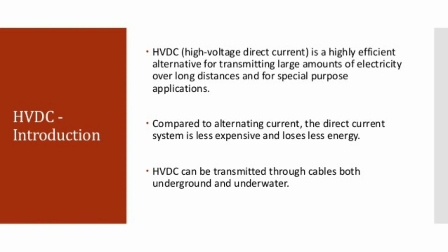But if you use HVDC system, the investment cost is lower and power controllability is easier, and here asynchronous interconnection is also possible, and we can transmit the power over longer distances, water crossing, and underground cables also we can transmit the power.